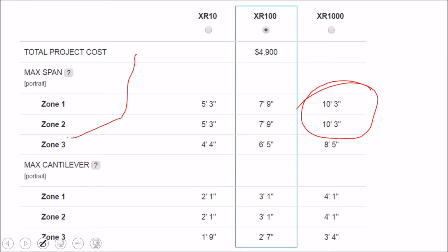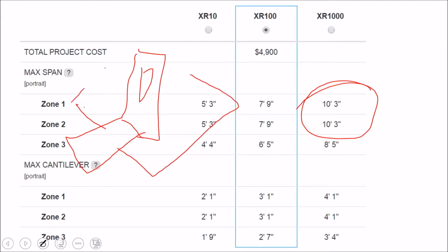Here's your L foot. That's your roof attachment. And usually nowadays there's some flashing that is integrated into the L foot. And then you have your lag screws that go into the deck. And this is a brand new penetration. Every shingle on the rooftop has roofing nails going through the roof, and they don't leak. And your brand new solar attachments usually don't leak.